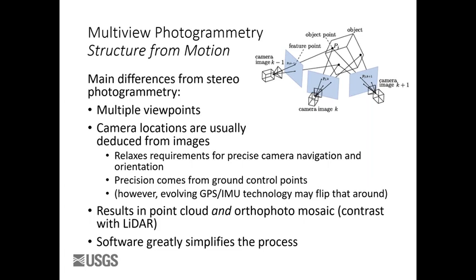But if you want to do photogrammetry and you want to measure things, you have to pin it down somehow. One way to pin it down is to know exactly where the camera is and where you're looking and what the geometry is. Turns out if you have a camera with a camera plane like this and it's looking over there, just the tiniest little bit of camera movement, just a slight angle, is going to have a big arc on the ground. If you invert it and flip it around and use things in the scene to lock down the camera, you get a lot more control.